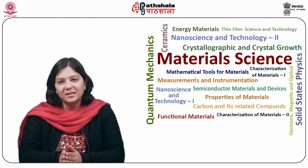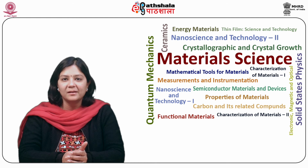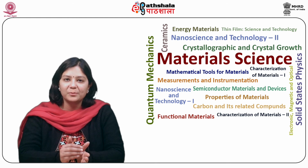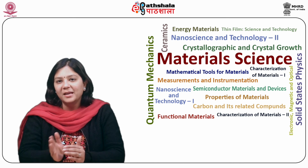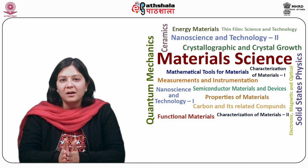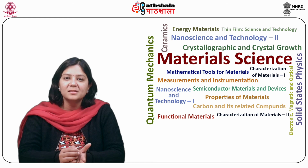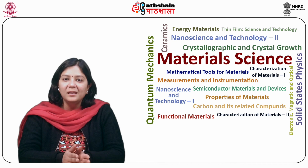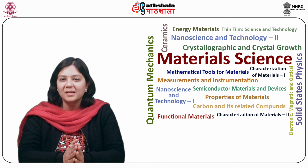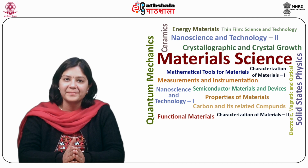A beam of a laser writer or electrons, or an e-beam writer, can be employed to expose the pattern produced by the data file. The beam is then moved over the substrate surface in either a vector or a raster scan manner. Where the photoresist on the mask is exposed, the chrome can be etched away, leaving a clear path for illumination light in the stepper or scanner system to travel through.